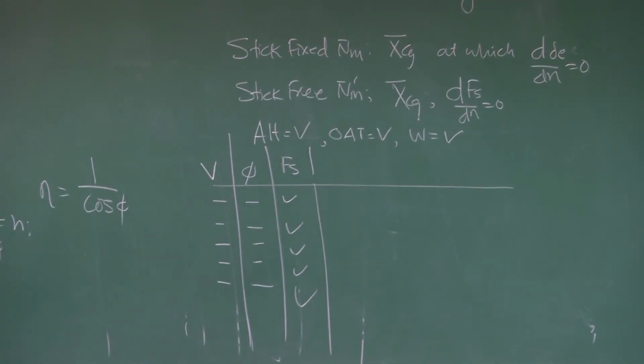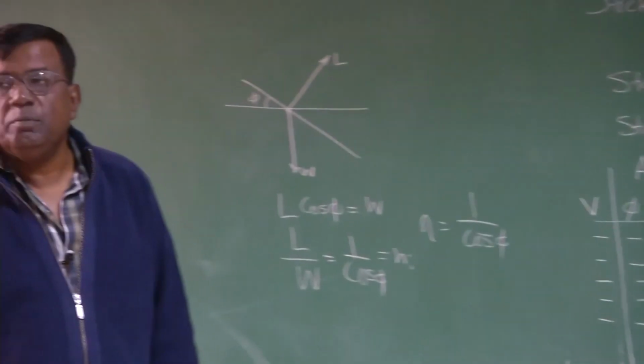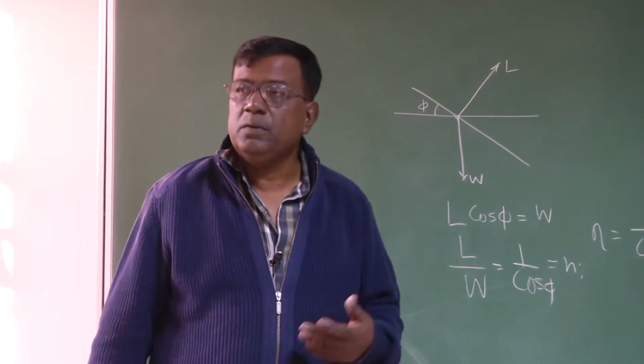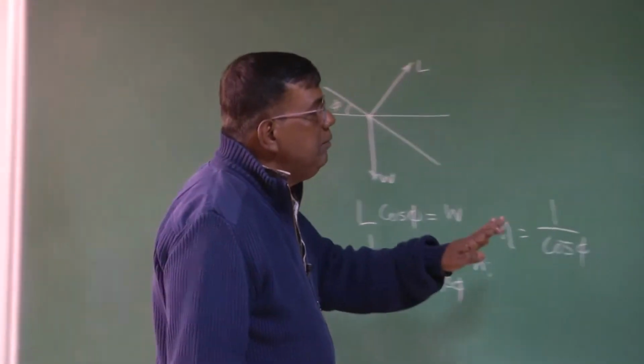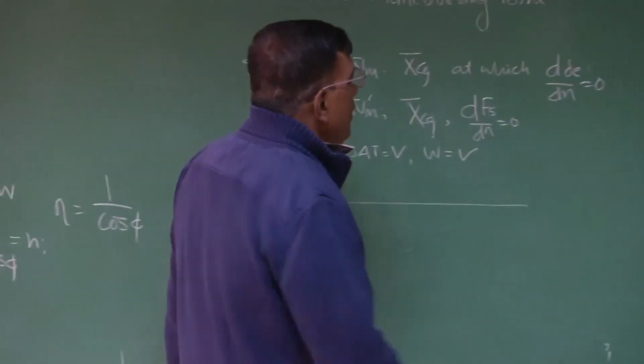Bank angle you get from the turn bank indicator. Stick force you will get from the strain gauge based stick. V from the airspeed indicator. And it goes without saying, you know that that speed is the equivalent airspeed, so you have to correct it for true airspeed by using the relationship. So once I have this, now you see what I will do.